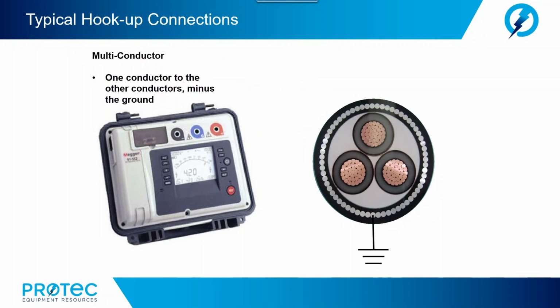All right, another possibility is we want to measure one conductor to the other conductors minus the ground. So now we're only interested in the current that is flowing from the conductor of interest to the other conductors, but we are no longer interested in the current that is flowing from the conductor of interest to the shield. So, once again, we jumper the two conductors. We connect the positive lead to the two conductors.